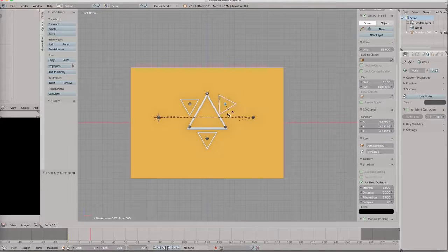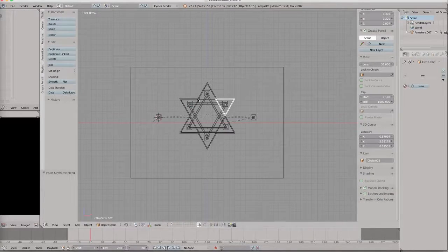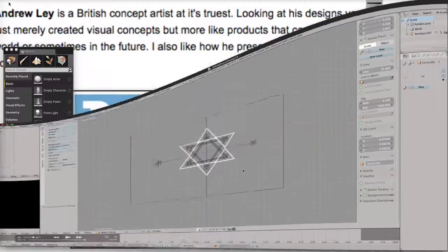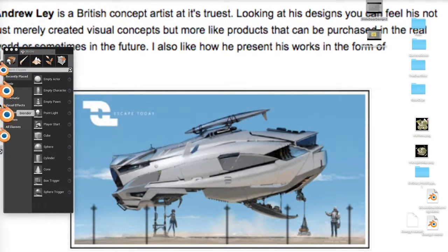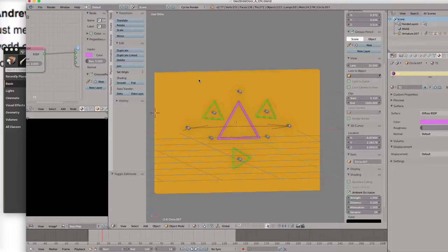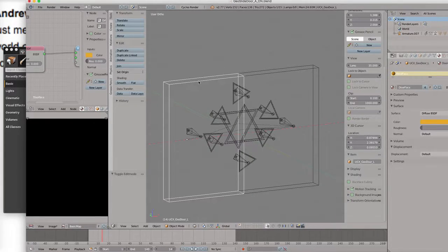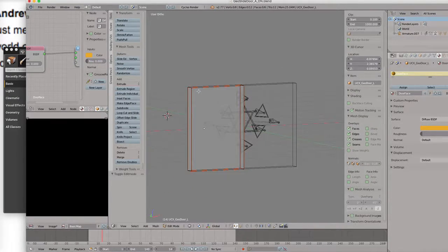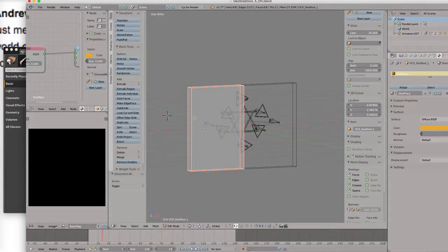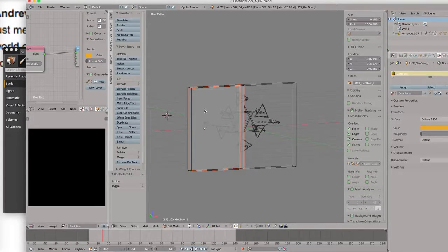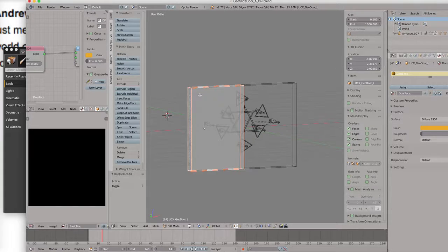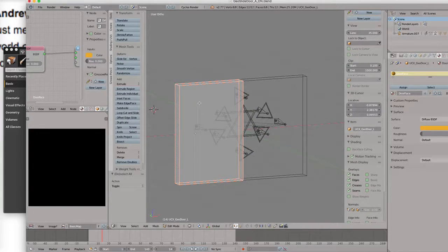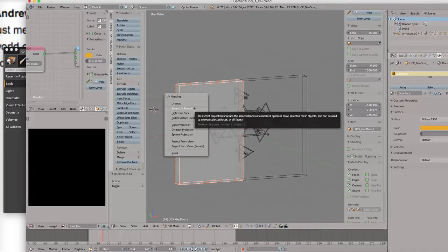I should probably illustrate that. I shouldn't assume that someone knows how to do a UV unwrap. So if you already know this, forgive me if it's tedious, but we'll go back in and I'll show it really quick. So in here, like I said, this door has some depth, and it probably would work if I just hit Tab and did a U and smart. So in object mode, hit Tab, edit mode, A, select all, U. Smart UV project would probably work fine.